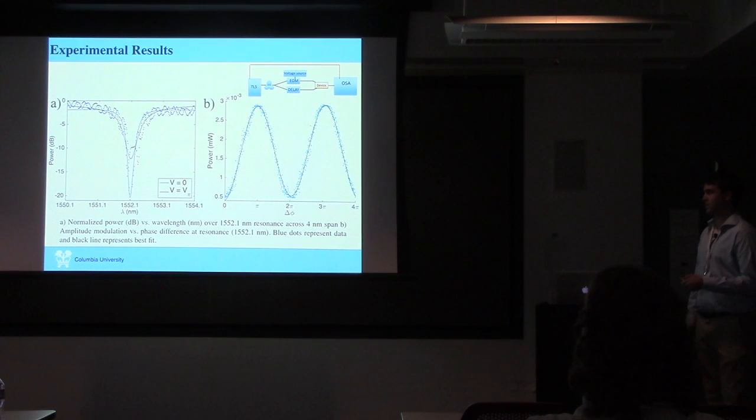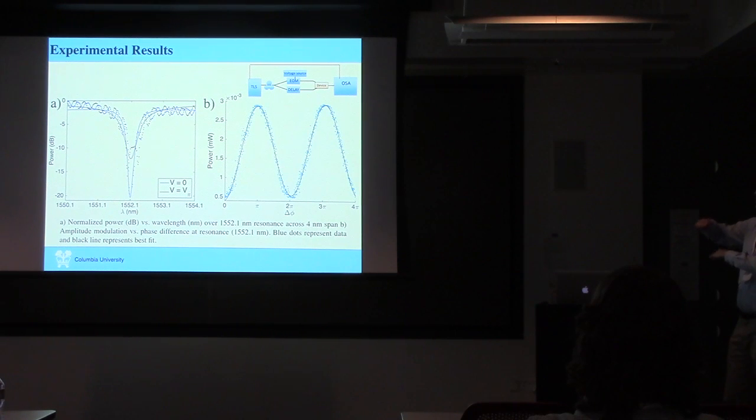If you look at only one, it wiggles around, and if you look at the other one, it wiggles around, and if you want to actually put data on it, it has to be very stable. The bit error rate needs to be like 10 to the negative 12, whereas we haven't measured a bit error rate on this, but it would probably be like 10 to the negative 3, if that. But any real device that uses data, like a Mach-Zehnder or something, uses on-chip delay. So I'm pretty sure a lot of it's due to that.